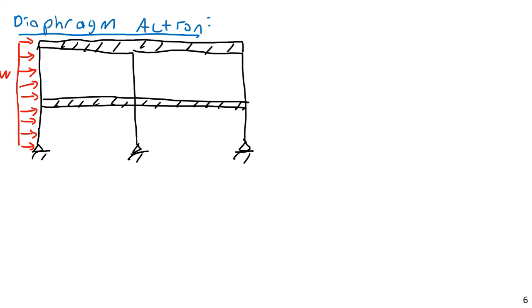The slightest breeze is going to knock that thing over. The window panels themselves do not resist load. They do resist it a slight amount. If you think about the lateral load right here, a window actually acts like a very tiny beam. It has to carry a teensy tiny bit of bending moment as it distributes the load to the slab above and the slab below. But in terms of the overall global building performance, they don't really carry a substantial load.